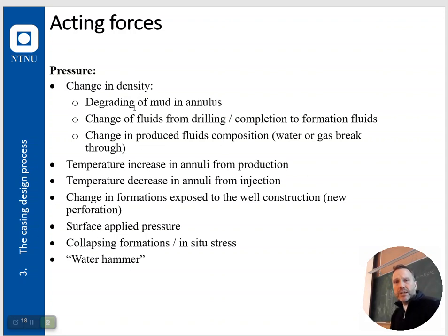Pressures, change in density, degrading of mud in the annulus, change of fluids from drilling completions to other fluids, change of production fluids composition. Let's say that you have water or gas breakthrough of your produced fluid. Temperature increase in the annulus from production or injection, change in formation exposed to the well. Let's say that you do perforation into a new formation. Surface applied pressures, collapsing formations, in situ stress, and the water hammer that we just talked about. These are pressure forces that act on our casings.